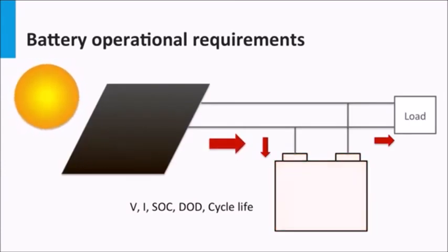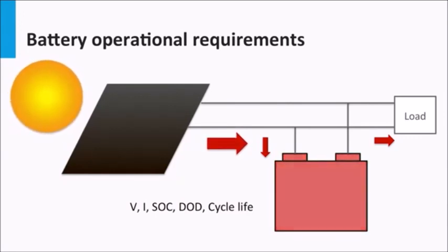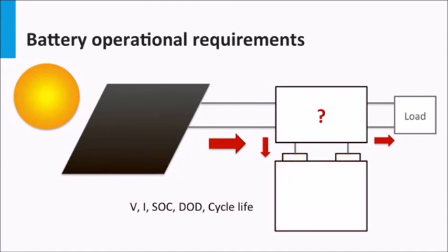You have also seen previously how a lead-acid battery responds poorly to overcharge and overdischarge. You also know how the PV array responds dynamically to ambient conditions like irradiance, temperature, and other factors like shading. Under such circumstances, a direct coupling between a PV array, battery, and load is far from healthy for the battery. This means that we need a device that can interface three-way between the PV system, the battery, and the load, and ensure that the electrical parameters around the battery are maintained within the battery manufacturer's specifications. This is where the charge controller comes in.